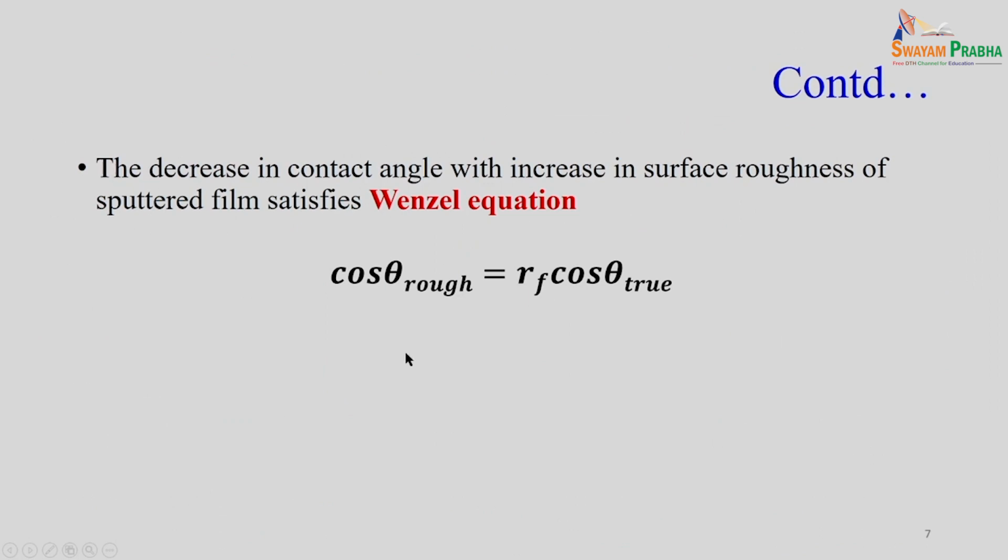Now, we tried to relate the surface roughness with the wettability, and we found that it agreed to the Wenzel equation, which says that the contact angle on a rough surface is RF, the roughness factor, times the true contact angle.